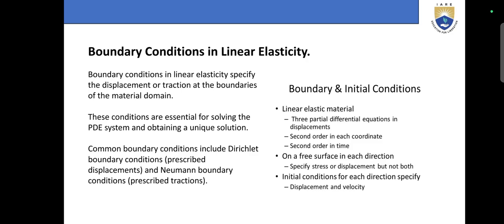Next, boundary conditions in linear elasticity. Boundary conditions in linear elasticity: the partial differential equations in displacement are second order in each coordinate and second order in time. On a free surface, in each direction we specify stress or displacement, and initial conditions specify displacement and velocity.